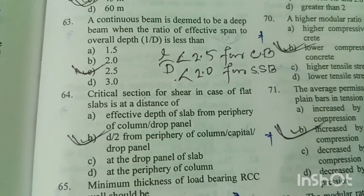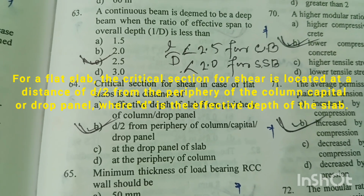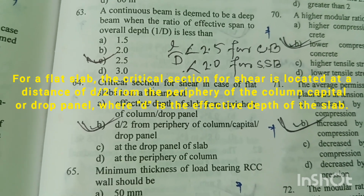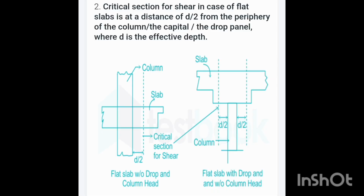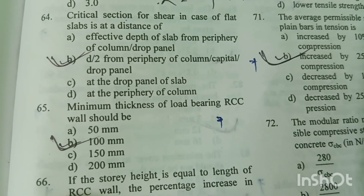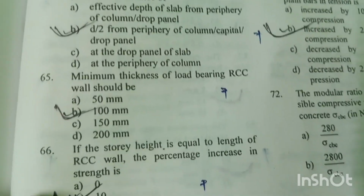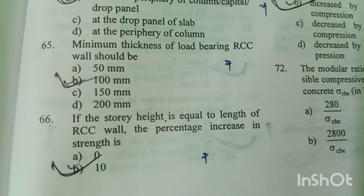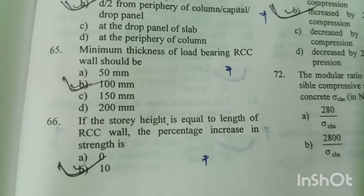Question number 64. Critical section for shear in case of a flat slab is at a distance of d by 2 from the periphery of the column or capital or drop panel. Option B is the right answer. Question number 65. Minimum thickness of load bearing RCC wall should be 100 mm. Option B is the right answer. Question number 66. If the story height is equal to the length of the RCC wall, the percentage increase in strength is 10. Option B is the right answer.